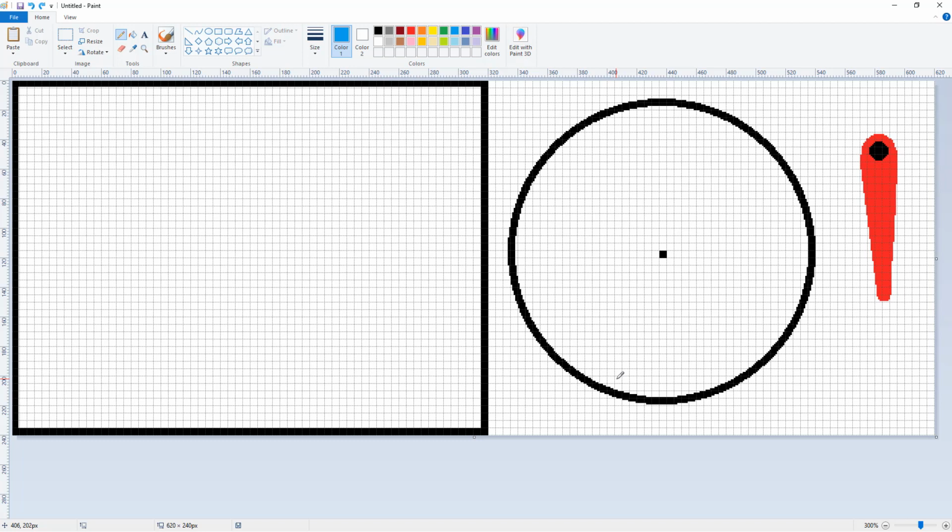And the problem with that is as you start to add more and more elements on the screen, you're going to start to notice the amount of time it takes to draw those elements, and it's going to show up as a flicker. You can have some buffers and you can start to delay certain aspects of it, but ultimately you're going to get to a point where visually it doesn't look good. Now, on these small screens with a limited number of pixels, it's fine. You'll also notice that if you display images such as a bitmap that you've converted to hex data or binary data, depending on the images you're working with, you'll notice the amount of time it takes to display those on the screen.